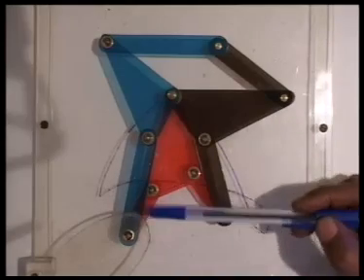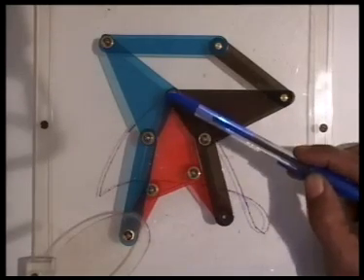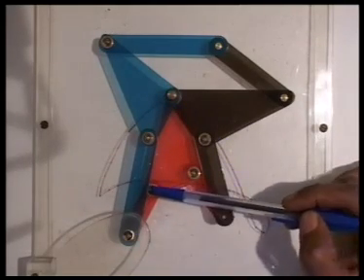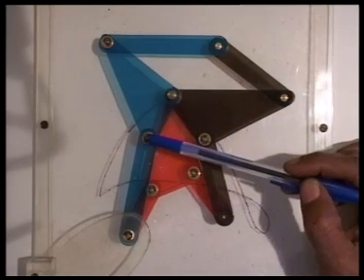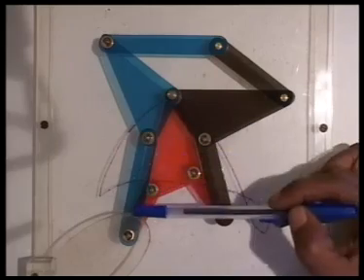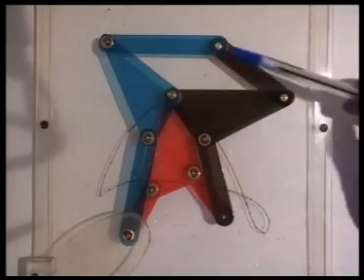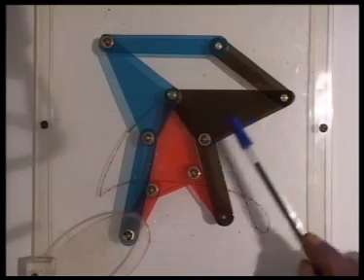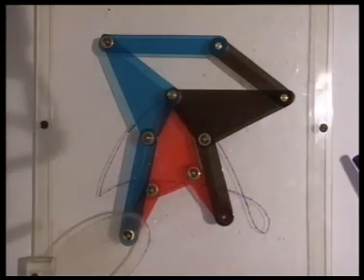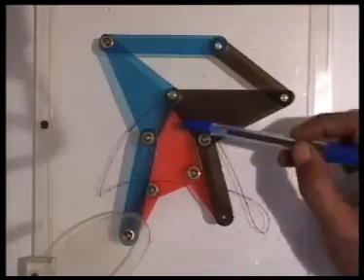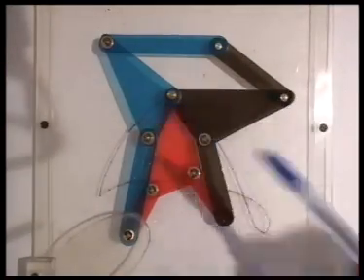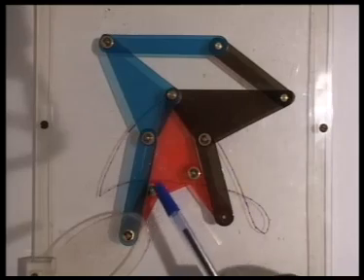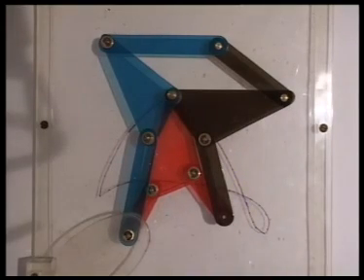We also note that this link length is equal to this link length and this link length is equal to this link length. Thus, this point O2, A, and this was C and this was D probably, form a parallelogram. Similarly, we have a parallelogram here and we have a parallelogram there. And these three ternary links, the red ternary link, the gray ternary link and the blue ternary link, are similar triangles. That means this angle is equal to this angle, and this angle is equal to this angle. We have seen that as a consequence of these special dimensions, these 10-link mechanisms move in a unique fashion because it has single degree of freedom.